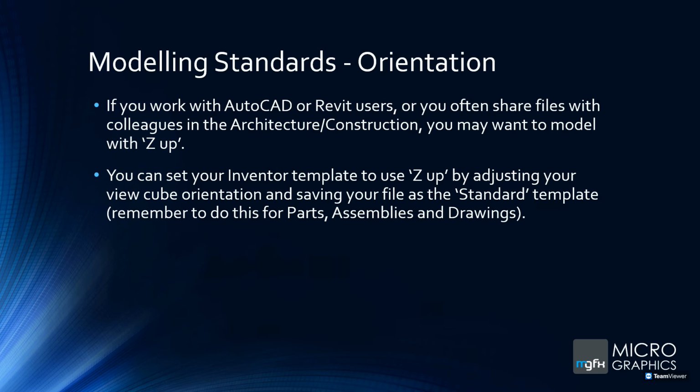Okay. And then, as I said, please look at your standard templates. If you've got quick standard templates, save it as standard.ipt, standard.iam, or standard.dwg or idw.